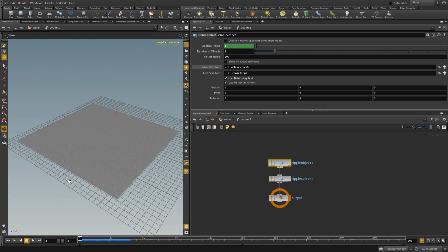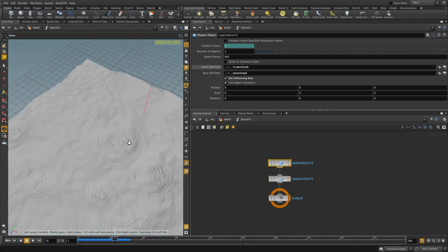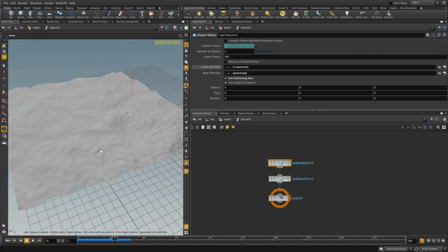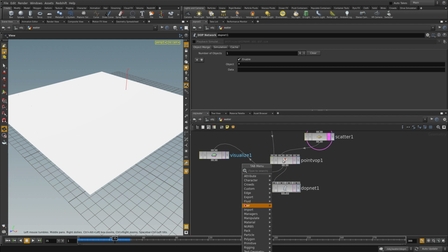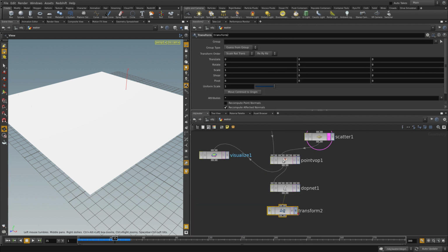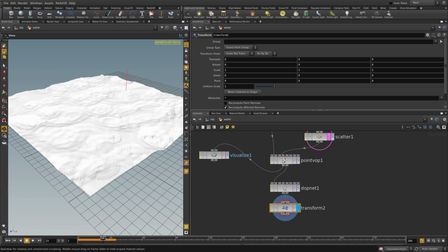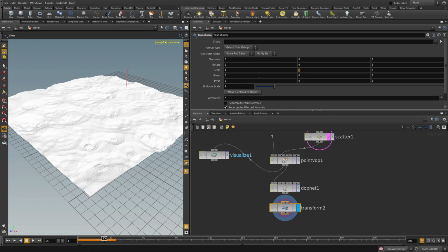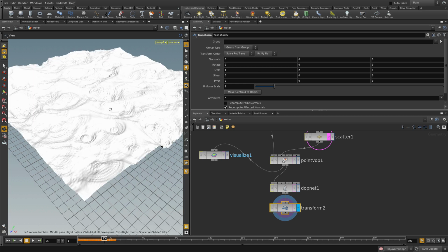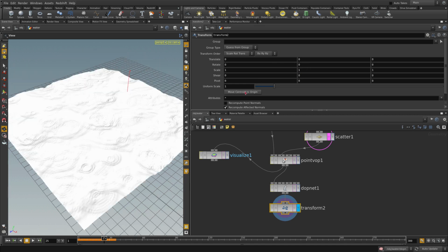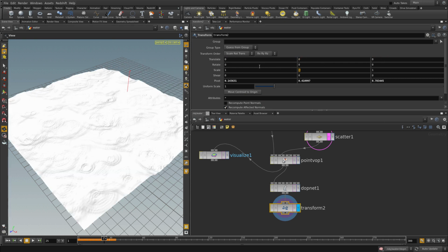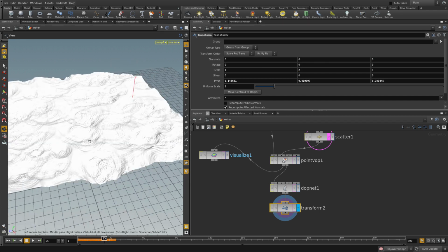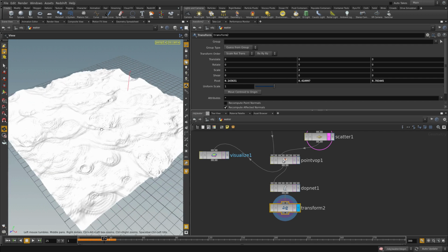And there you have it. That's basically it. This is the ripple solver. Now it's creating these dents here. Very nice. What we can do now to make the effect a little bit more apparent is go one level up and just append a transform here and just scale it to say 2 in Y. But before we do this, we quickly click move centroid to origin, then get rid of the translate, and then do this again like so. Makes the effect more apparent, as you can see.